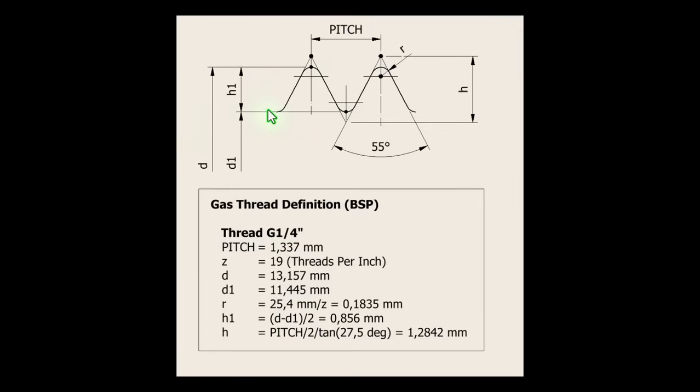We continue with creating this profile, only one pitch. This dimension is equal to this dimension. The pitch is this dimension. Then we have to place this point at the start of the thread.